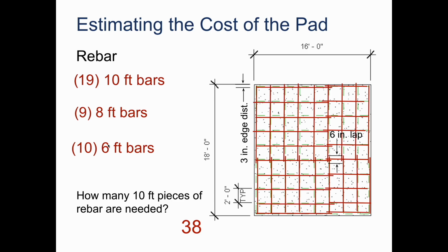Some of y'all might be thinking, well, hey, we've got it where these are 6-foot pieces here, right? We can end up using the other 4-foot piece that's cut out from this. We could add 2 of those together, right? We could create this 8-foot bar. We don't really want to do that because there actually is a requirement for your rebar that you want to not have too much overlap. So if we do have those small pieces and we're consistently overlapping it, it's basically not good most of the time in codes. It could be a code violation if there's too many overlaps in there. I think that they have a minimum requirement. There's also a minimum requirement for how long your rebar is too. So in this case, we just want to end up using the 8-foot bar sections and 6-foot bar sections.